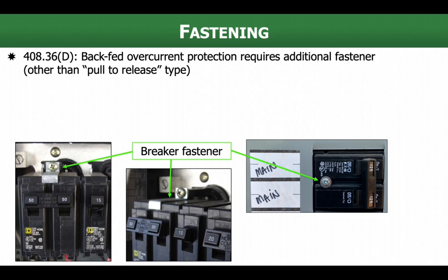And this kind of makes sense. Let's say that one of these breakers here is connected to a generator, and you're backfeeding it from a generator. Well, what happens if I take that breaker? Let's pretend the fastener's not there. It's just a regular plug-in breaker. The generator's running. I take the breaker, I pull it off the bus bar. What am I holding in my hand? I'm holding the output of the generator. That breaker is still energized. That's dangerous.